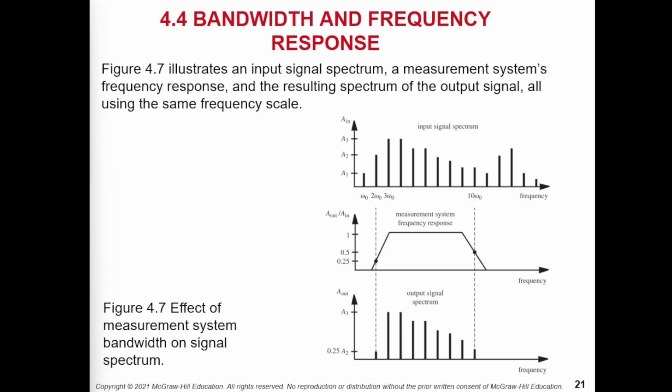So within the bandwidth, it's bypassed, and above or below the bandwidth is attenuation, so the ratio is less than 1. If you transfer to dB, it will become 0 here, and all the values here will become negative. So it's very obvious to me. But I know some DSP engineers would like to see this in linear scale. So either one is okay.